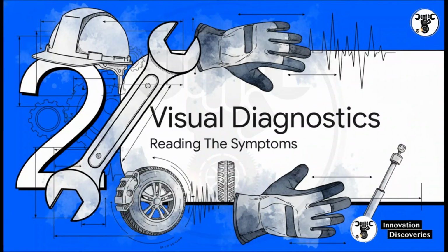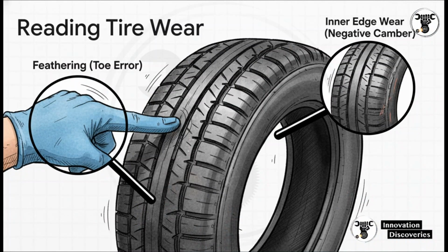Moving right along, Section 2, Visual Diagnostics and Handling Symptoms. Let's take all that dynamic theory and translate it into visual evidence you can actually use on the shop floor. A technician's absolute best diagnostic tool is often sitting right there on the rim, the tire itself. Inner edge wear, that points to excessive negative camber. Outer edge wear, you're looking at excessive positive camber. But the real trick is reading what we call feathering.